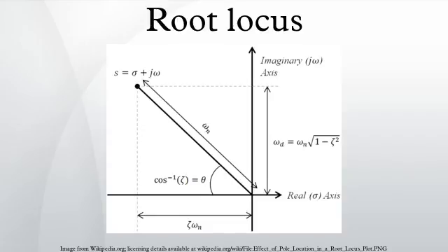More elaborate techniques of controller design using the root locus are available in most control textbooks. For instance, lag, lead, PI, PD and PID controllers can be designed approximately with this technique. The definition of the damping ratio and natural frequency presumes that the overall feedback system is well approximated by a second-order system. That is, the system has a dominant pair of poles. This is often not the case, so it is good practice to simulate the final design to check if the project goals are satisfied.